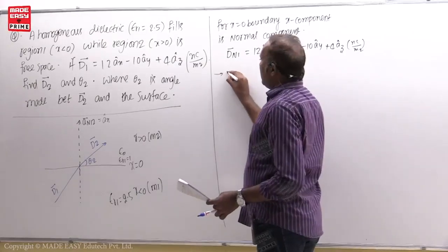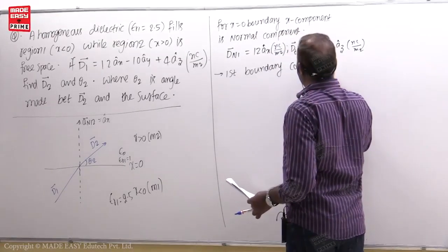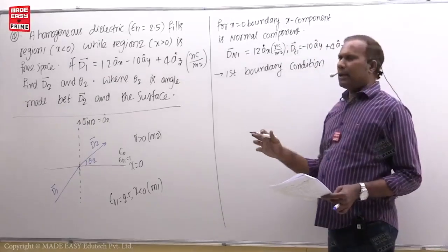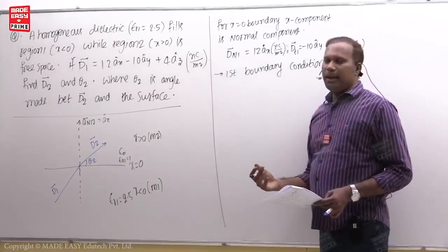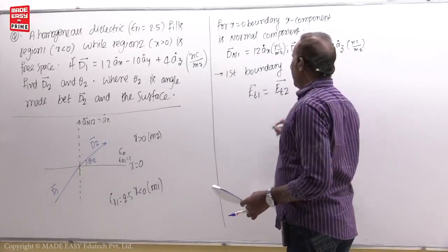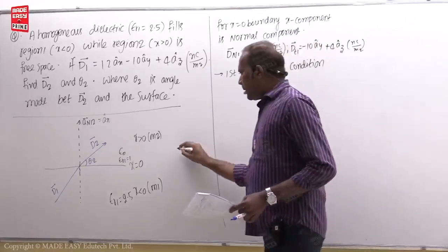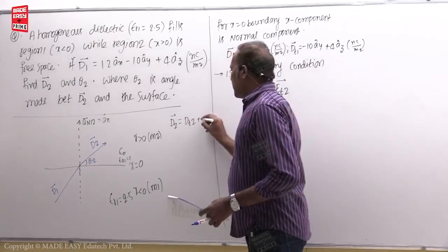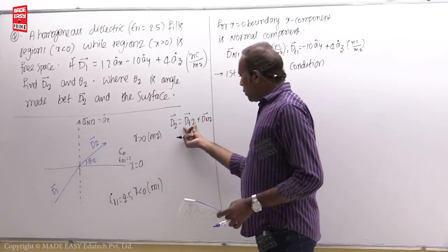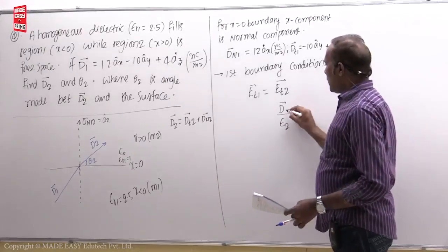Now, the first boundary condition, because the electric fields in medium 1 are given; electric fields means E bar, D bar, they are commonly called electric fields. You have to find the fields in medium 2, so the first and second boundary conditions are used. The first boundary condition is Et1 bar is equal to Et2 bar. Now D2 bar is equal to Dt2 plus Dn2. If you want D2, find these separately. Now you want D2 bar, so write this in terms of D. Electric field is equal to D bar divided by epsilon, for medium 2 it is epsilon 2.